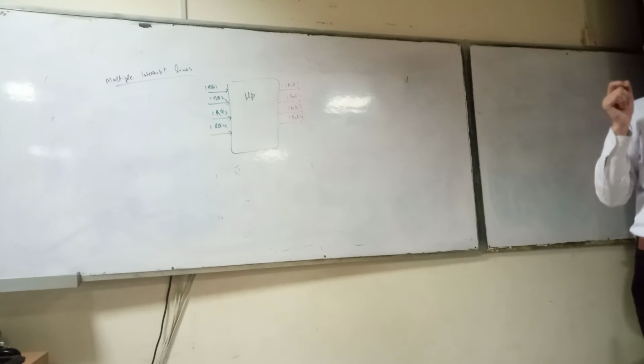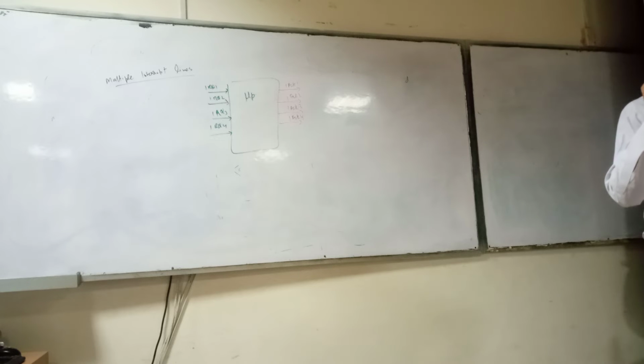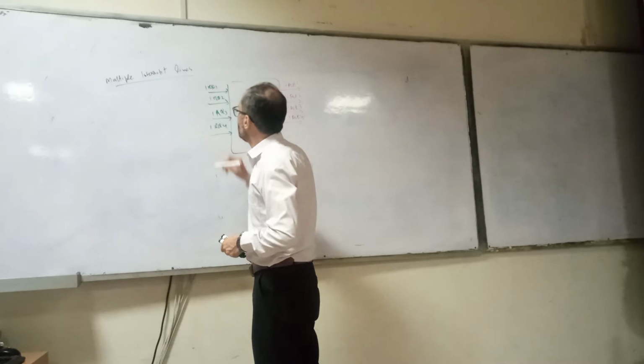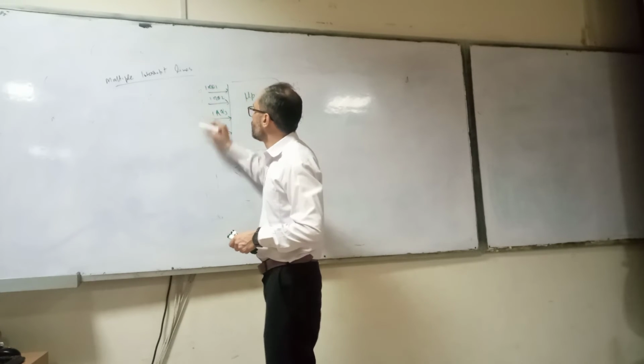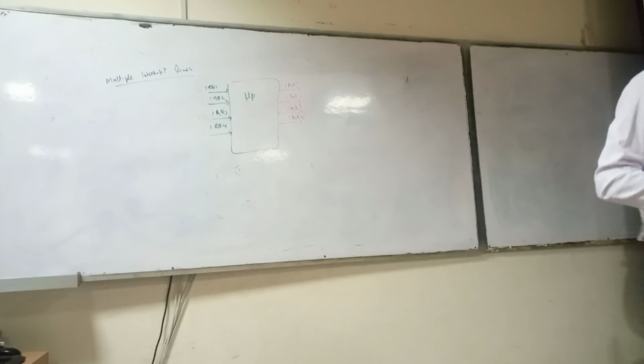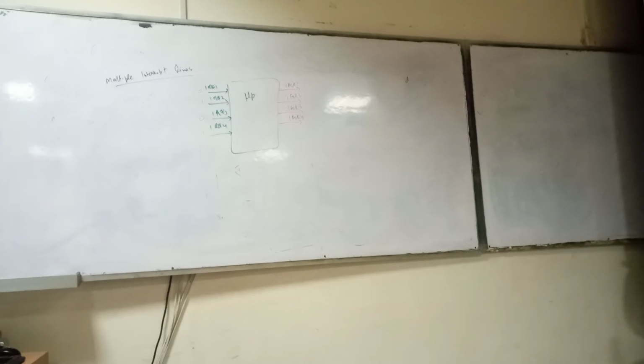The microprocessor will know exactly which device has generated an interrupt. Let's assume it is active high, so 1 and 1, and 0 and 0. What does it imply? Which of the devices generated an interrupt? Devices 2 and 4 generated an interrupt. But the microprocessor can service only one of them at a time. So there can be some priorities.